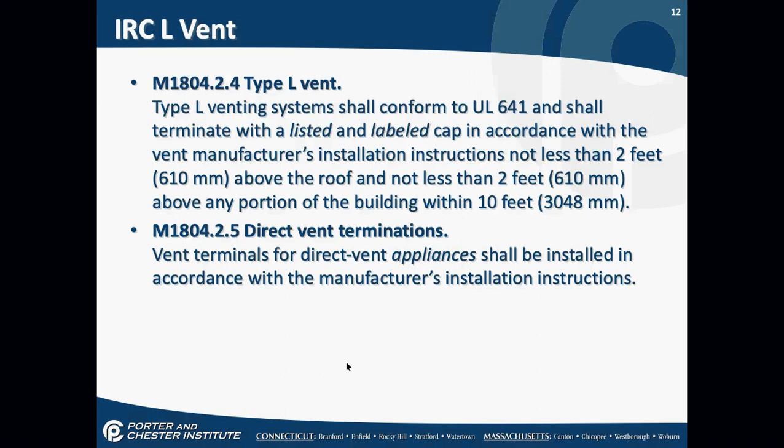Basically, the insurance company started Underwriter's Laboratory because they wanted an independent third party to check all of these appliances, check all of this electrical equipment and stuff like that to make sure it's not going to burn buildings down or hurt people. Okay, so everything has to conform to Underwriter's Laboratory requirements. Vent terminals for direct vent appliances need to be installed in accordance with manufacturer's installation instructions.